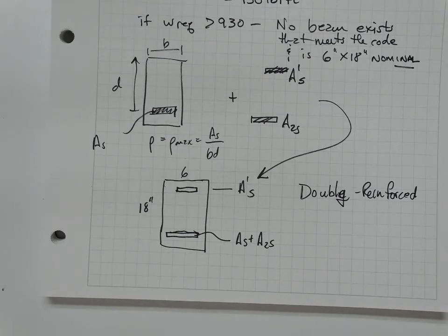And crew number 2 can put up the forms for the beams 35, 50, 200 feet away. And then I can take the tied together beam, pick it up with a crane, swing it in place, and put it in the forms. Now you're taking scheduling. Rather than doing erect the forms, then tie the steel, I erect the forms and tie the steel and marry them together at the end. Right? Makes it easier to construct.